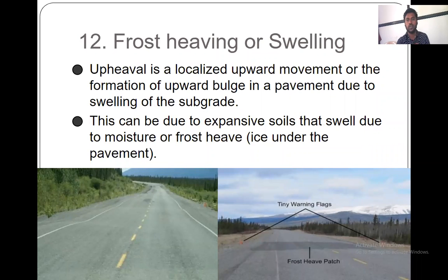Frost heaving or swelling: these roads are formed due to improper foundation or improper bearing capacity of the layers beneath. Such undulations are found on the layer. You can observe the frost heaving or swelling on the road in the figure.